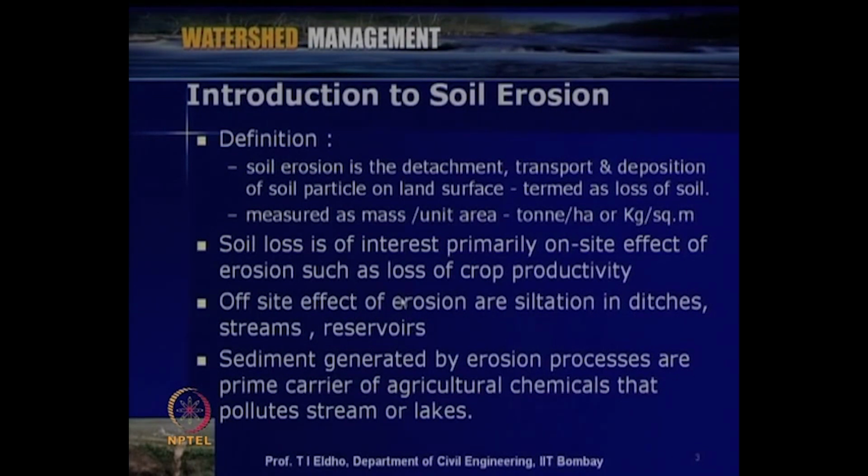When the soil is eroded, it is carried as sediment by the running water within the runoff, taken through the streams and rivers, and may reach lakes and reservoirs and finally the ocean. That way there are problems of sedimentation in reservoirs, streams and lakes.